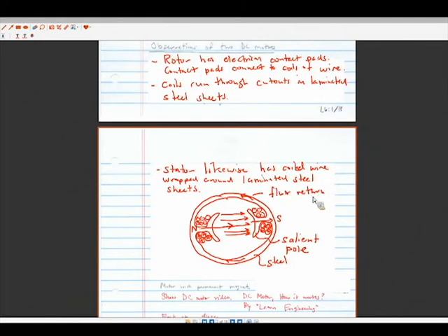We'll get into more on this in a bit. We're going to start talking about the contactors, and we'll also talk about this motor as well, which is slightly different. The one being passed around has coils that create the magnetic field. This one actually has a permanent magnet that creates the magnetic field. So permanent magnet motors are also wound coil DC motors. This one's in pretty bad shape. You can take a look at what happens to the contactors and brushes over a bit of time, and you can also see the laminations in the rotor a little better in this one. But I'll have to wait till Wednesday.